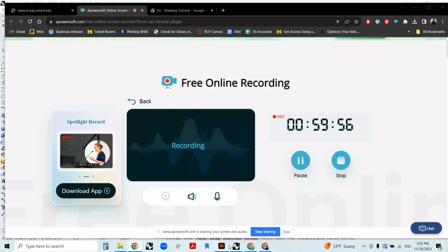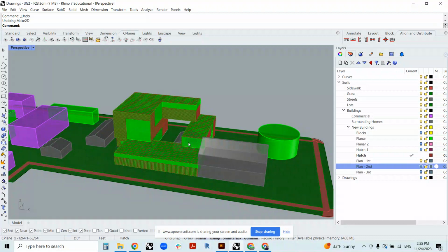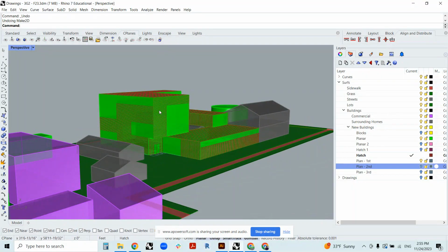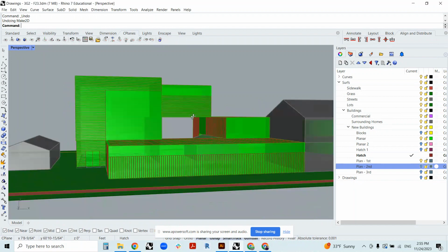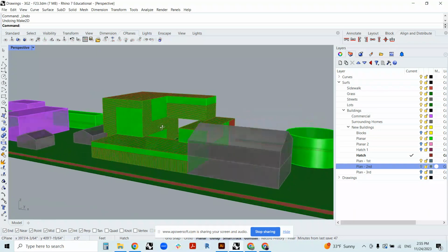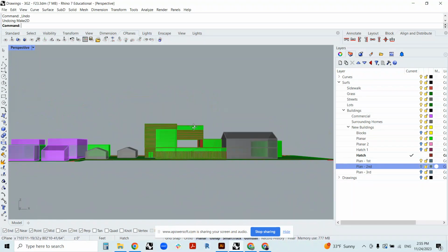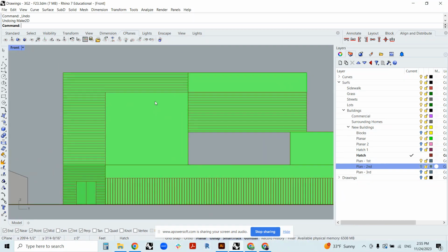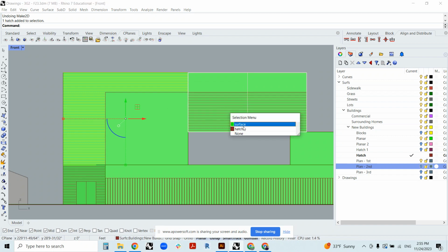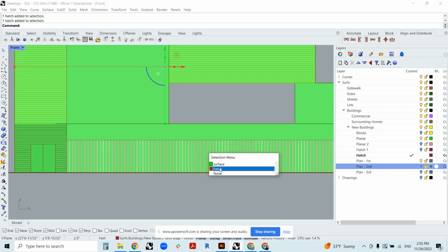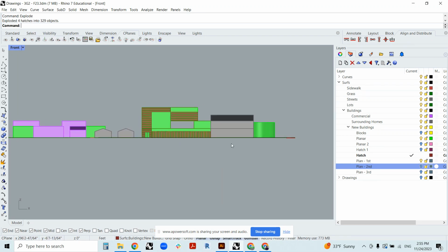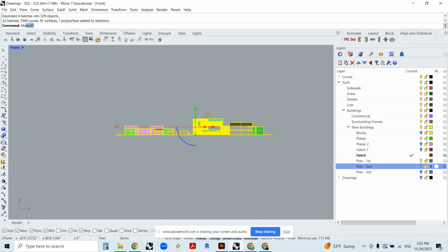Next, we're going to talk about developing your model now into an elevation. So the last video discussed using hatches to approximate or represent materials. And then if you want to do an elevation, again, start with make 2D. You need to explode the hatches in order to see them. So you could just go into the view that you're looking for and then explode, make 2D.